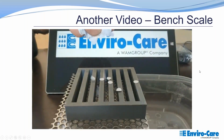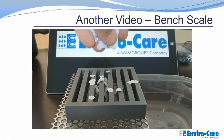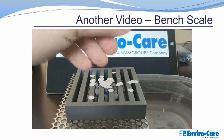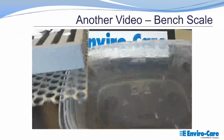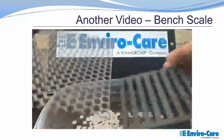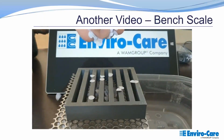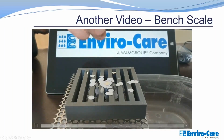I used to do it at the engineering offices and plants that I visited, up until they asked me to stop making a mess. But the idea being, this is a 6 millimeter bar over a 6 millimeter perf, or 1/4 inch for those of us here in America. You can see a lot of materials caught by that bar screen, which is why we commonly associate a 1/4 inch bar screen as being a fine screen, but a lot more materials caught by that perf screen. And that's really where one of the common disconnects come in, and where the independent testing has shown there's a significant difference in capture rate.